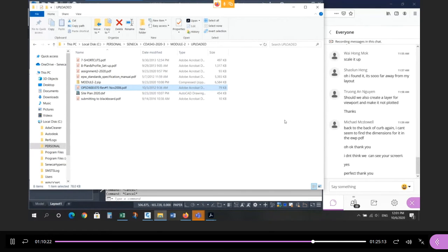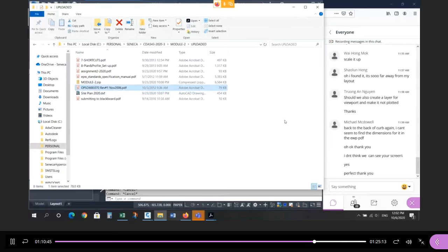So we'll have a new set of standards, but we have to look up the same type of stuff, right? What road section am I using? What curb and gutter detail are they using? What's pavement width, and what does that mean? Is it asphalt? Is it edge of pavement? Where do the sewers go based on the cross section, right? So you're looking for the same information to do your work, but the information may be different in the details when you look at a different municipality standard, right?